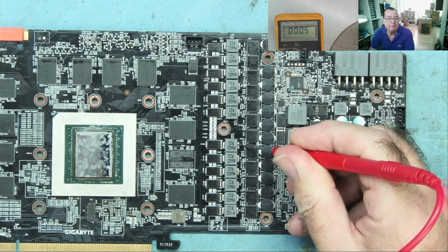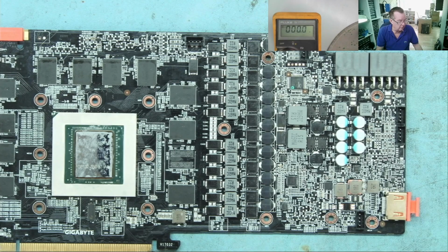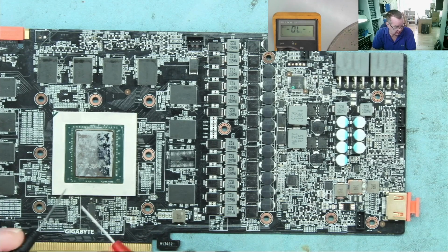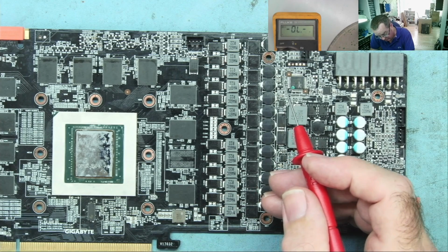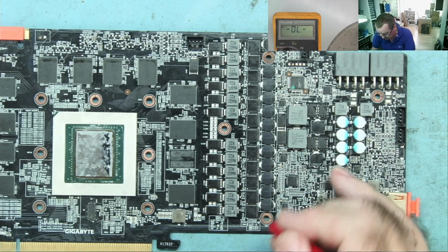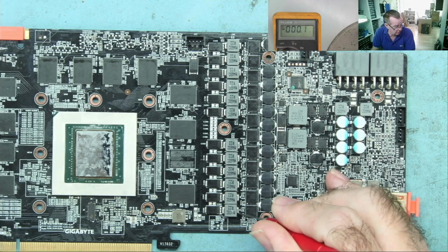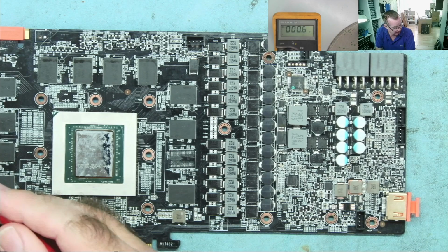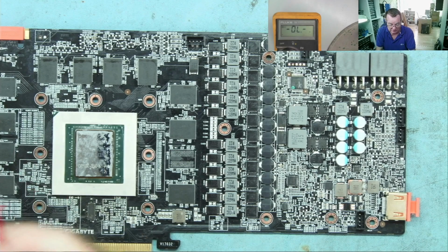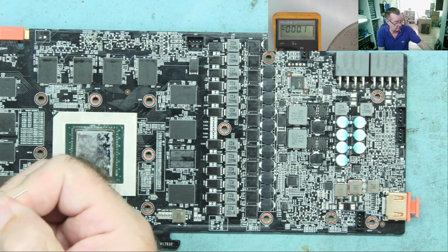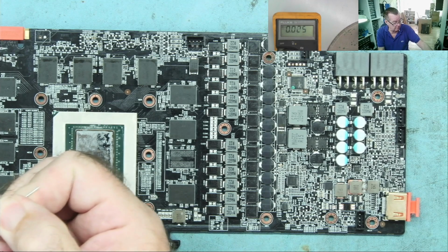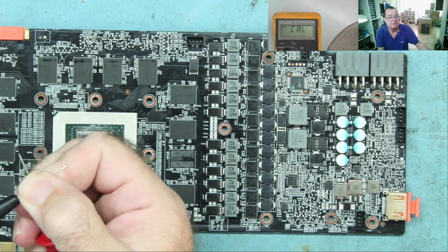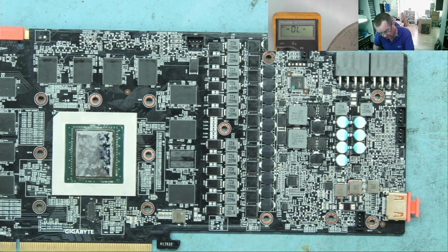Well, it reads 0.5. I put my meter into the lower resistance range and I've just zeroed it. So it's now zeroed, yeah. It's not in diode mode, it's in resistance mode. What have I got? Well, that actually reads less than 0. I mean, I probably had a better connection actually. Zero it again. Calibrate. 0.